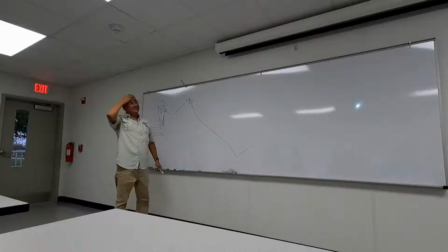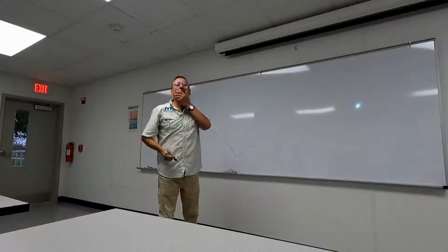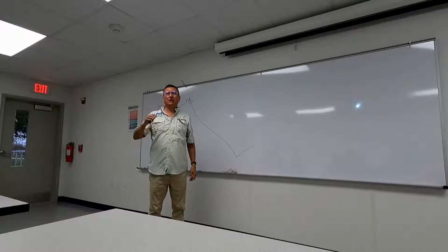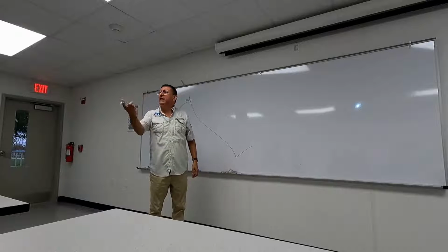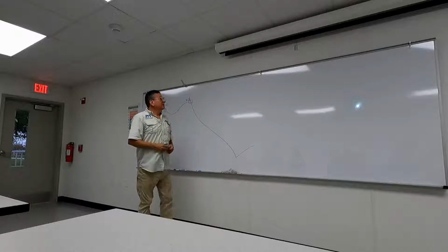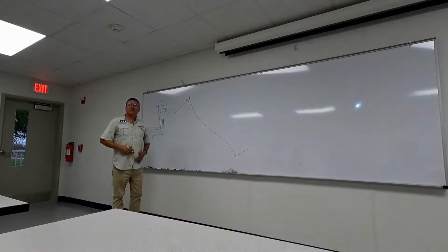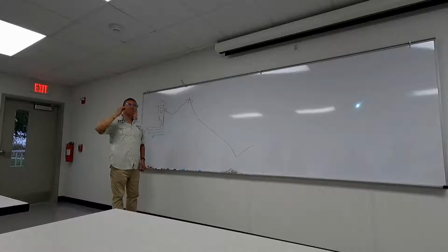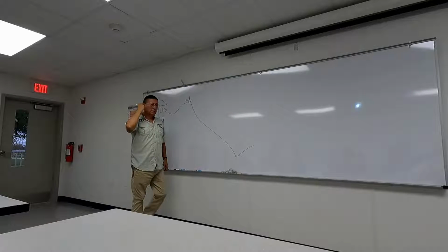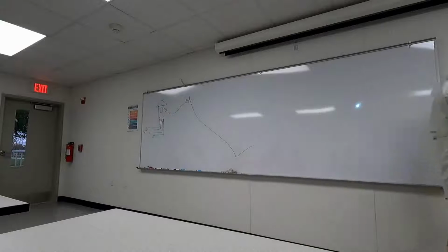Yeah, Steve just made a point. It's not the voltage that kills you, it's the amps. Yeah, and you don't need a lot of amps. It's with 20 milliamps. Wait, how many did you say? All right. Well, just put it this way, on the outboards or stern drive, the voltage coming out of the ignition coil is about 40,000 volts. That doesn't have a lot of amperage. So you'll get shocked, it'll hurt. It's not that bad. I mean, I get shocked all the time, but it's not something that's going to knock you on your ass.